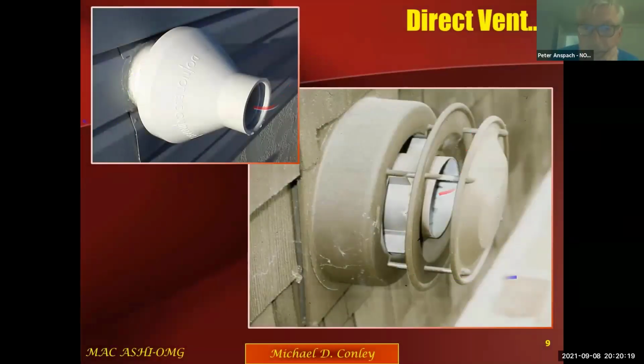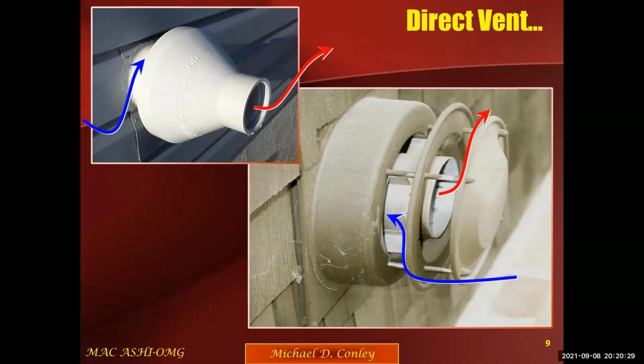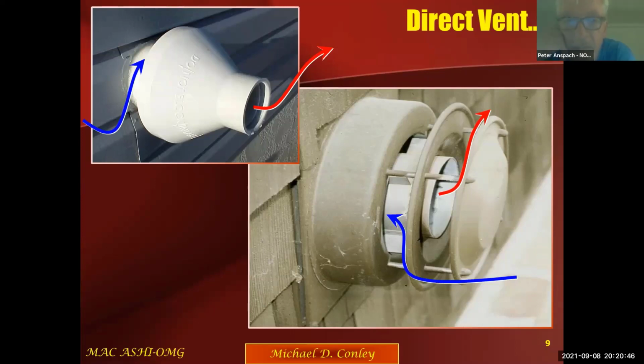Hey, Mike, real quick, what's your opinion on those screens going over those vent pipes to keep vermin out? I don't run across them in my market area, so I really don't have an opinion. If the manufacturer says they're okay to use, then I would be comfortable with that. But I've yet to see that in any specifications where they actually address that issue. Yeah, I see them sometimes pressed inside the piece of PVC pipe just to keep critters and birds from going in there. But that's a homemade job.